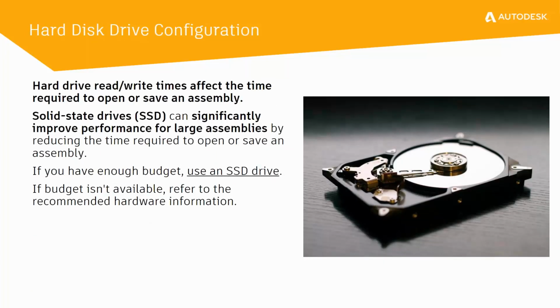Hard disk drive configuration. When it comes to hard disks, there's a number of things we'll talk about over the next few slides. Firstly, hard drive read-write times can affect and quite often significantly impact the time required to open and save an assembly. As such, a solid-state drive or an SSD can have significant improvement in performance when working with large assemblies over traditional drives. So if you've got the budget, and I would like to think that most people would have the budget, especially when they recognize the performance trade-off of using an SSD, then we would recommend that you do try and use SSDs where possible.